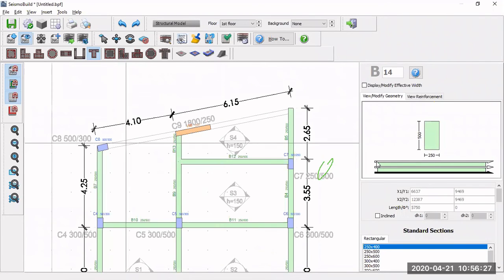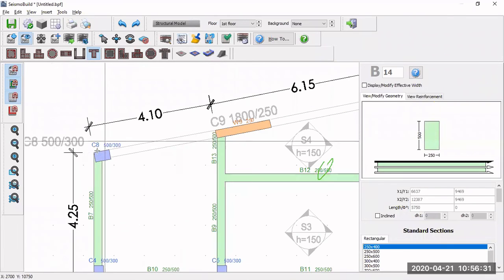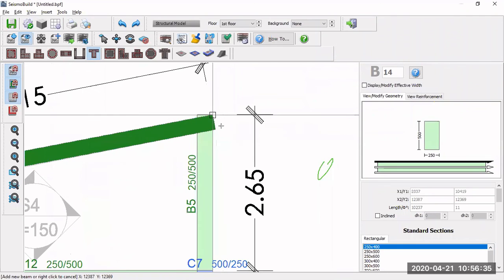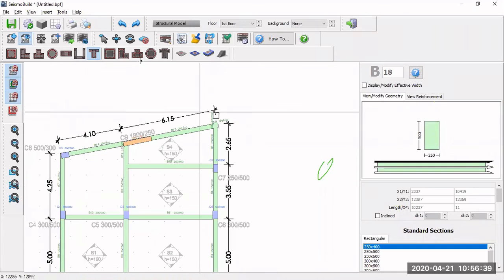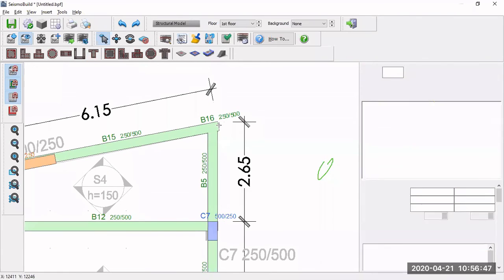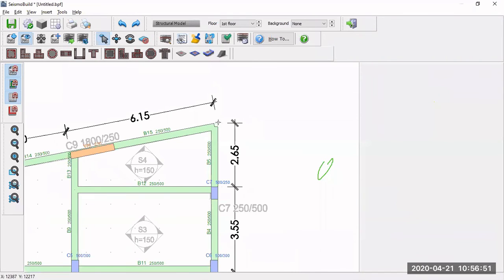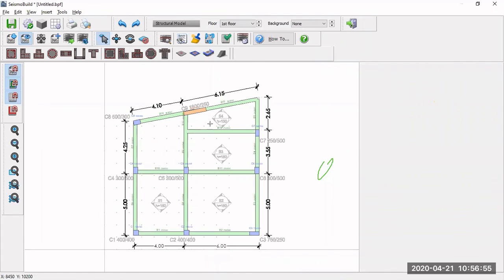And last, we want to insert the incline. We select the top inclination. Okay. So this corner to the top corner here. Okay, so we already done the whole beam for this floor. I noticed that there are two extra beams created over small bits here. We can delete them because we don't need that. They don't carry anything, so we delete them. So that's it. We complete the beam for the first floor already.